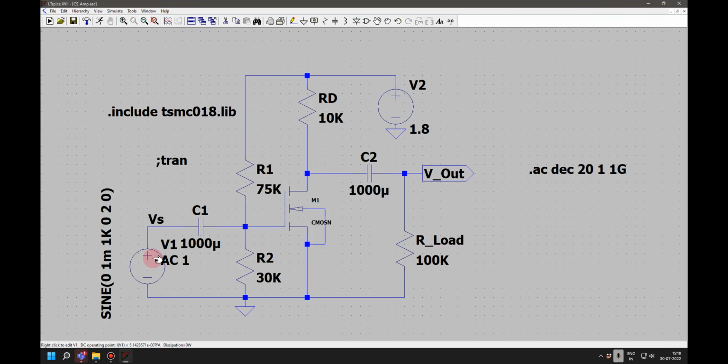Can we see that capacitance value, the CGD value? No, actually, in this particular software, it will not show. In Cadence, you can find out what is the value of CGD. Here you can open up the .lib file as a text document, open it in Notepad, then you will get all the equations which have been used for this transistor.